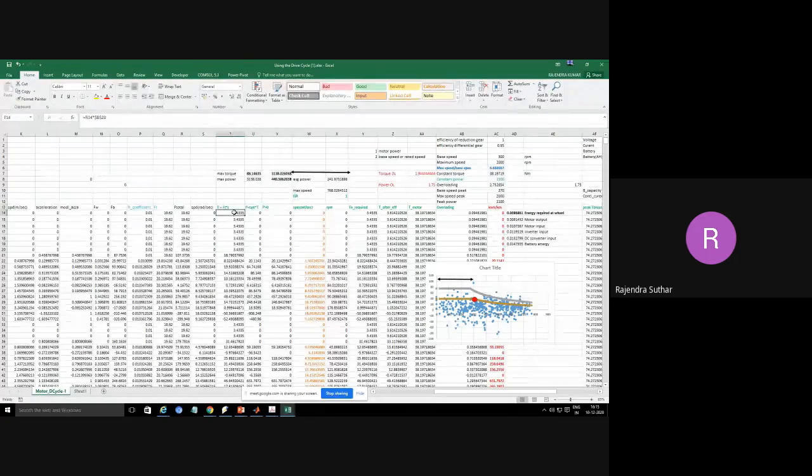So torque is calculated here, and omega is known to us, which we found from this wheel's radius and the speed of the vehicle. So using all these force data we calculated from the velocity data, from this force data we moved from this translatory motion to this rotating motion. So we found this wheel torque, and then the wheel's omega in radian per second.